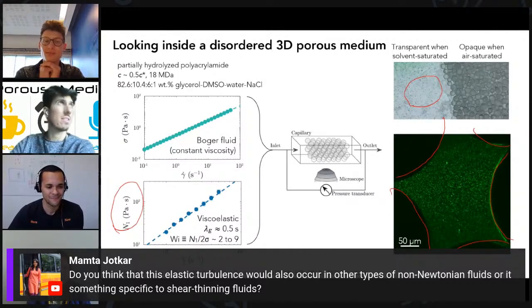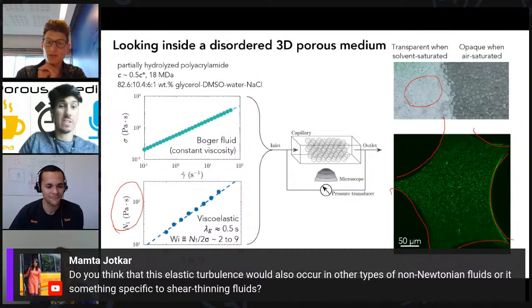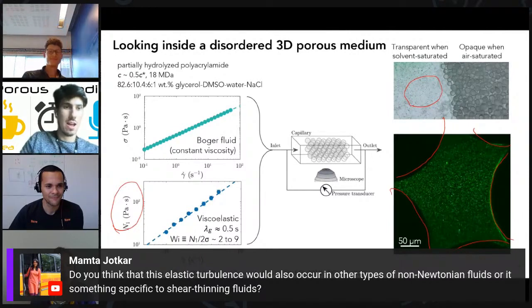Yeah, and I might add, if there is some yield stress effect in this fluid, maybe some strange effect might emerge due to the fact that there is this threshold to overcome. So I don't know if there is some yield stress fluid, so a fluid that presents not only a varying viscosity, but also a yield stress that you should overcome in order for the fluid to flow.